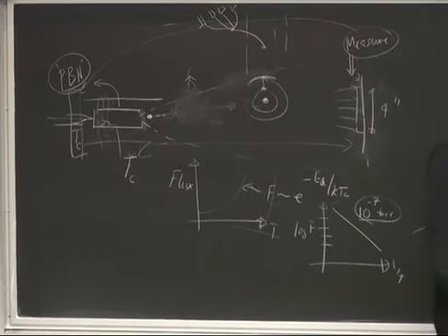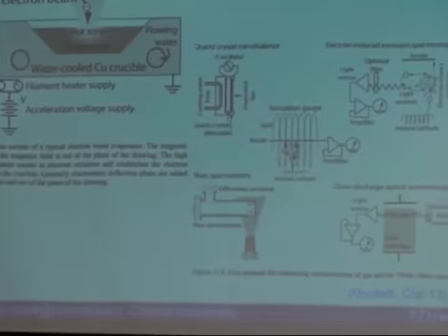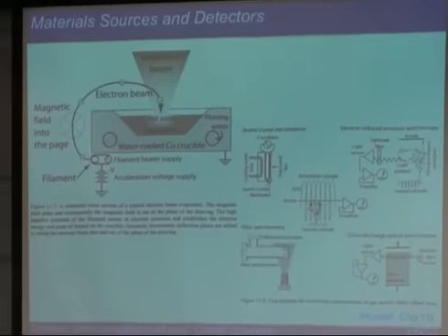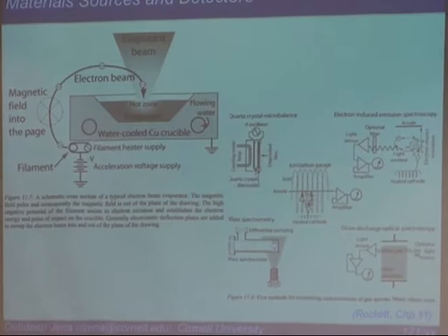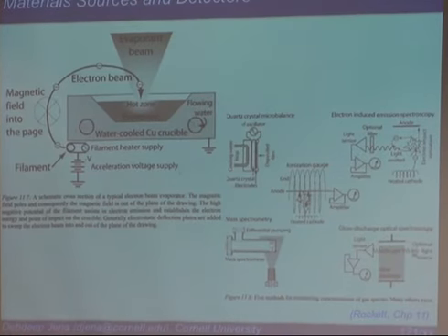Typically, ion gauges are very difficult to use if you're growing oxides, as an example. If you're growing oxide semiconductors or complex oxides, this is rather tricky because the filaments oxidize very fast chemically in that environment at high temperatures and high oxygen flux. Therefore, this is typically not preferred in an oxide system. Typically, you would be using a quartz crystal monitor in an oxide system. But for environments such as gallium arsenide or nitride systems, this is typically preferred. Okay, and it depends on many other details.